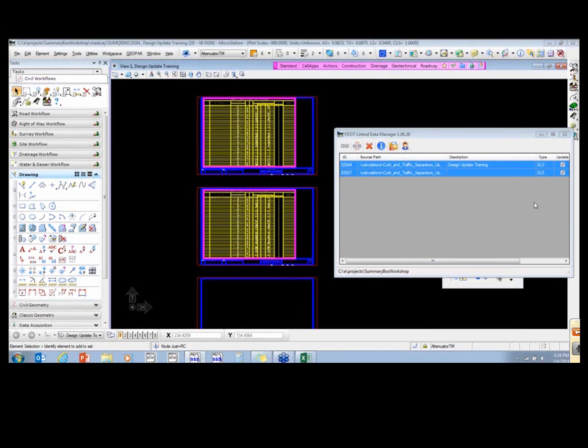If you have long lengths, so your main line is two 12-foot lanes on each side of a divided highway. So I've got 24 feet times the length of my project. You can use the length and width columns, because that's easy for construction to say, okay, length times width equals this amount.